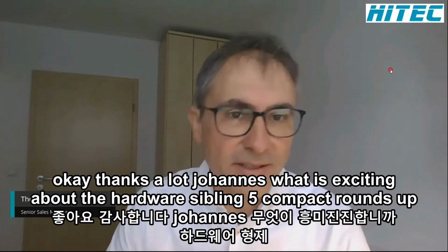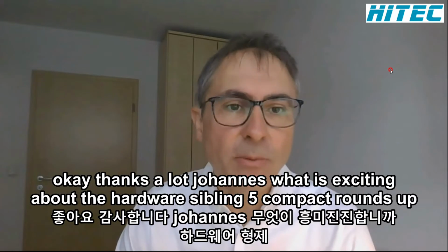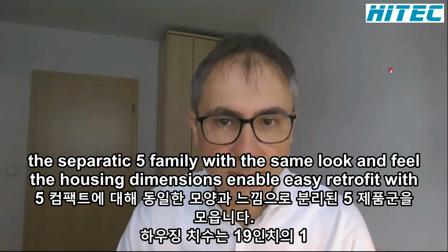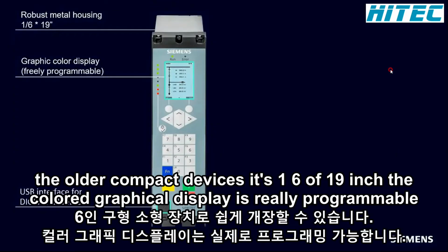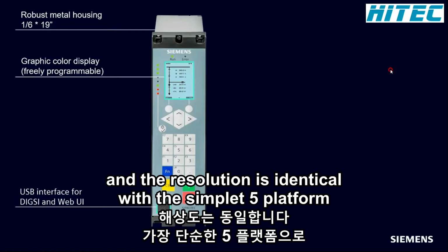Okay, thanks a lot, Johannes. What is exciting about the hardware? SIPROTEC 5 Compact rounds up the SIPROTEC 5 family with the same look and feel. The housing dimensions enable easy retrofit with the older compact devices. It's 1/6 of 19 inch. The colored graphical display is really programmable, and the resolution is identical with the SIPROTEC 5 platform.